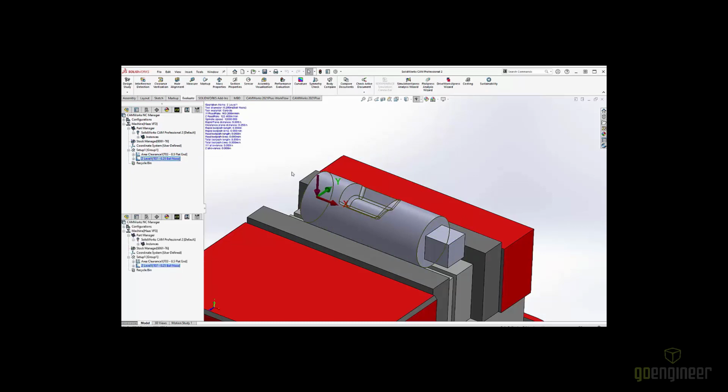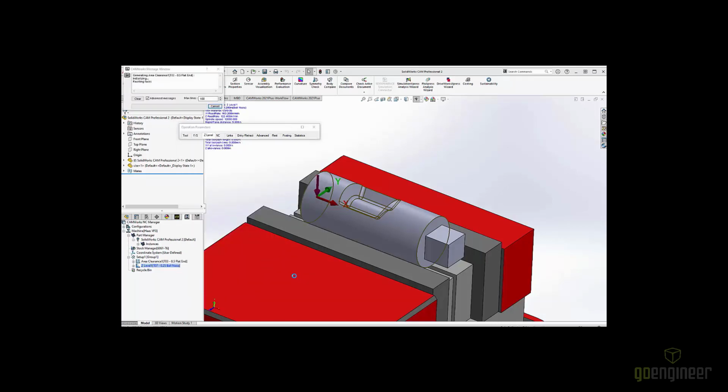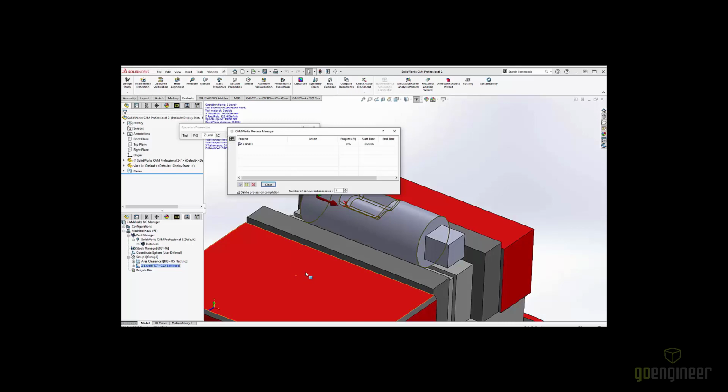Previously, it was limited to the Z planes, as I had shown. But in this case, with the SOLIDWORKS CAM Professional license, we can enable this checkbox for combination cycle. It's going to be able to deviate from that Z plane restriction, and get you a much more comprehensive toolpath, more capable of some of the trouble geometry that plagues the Z level toolpath.